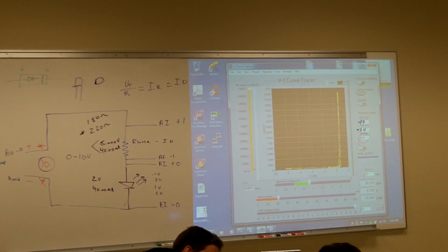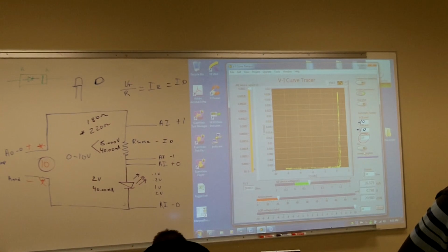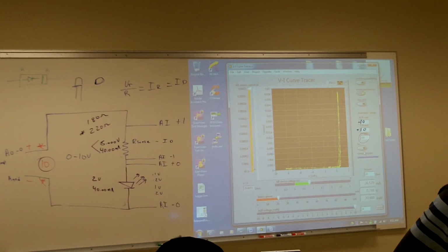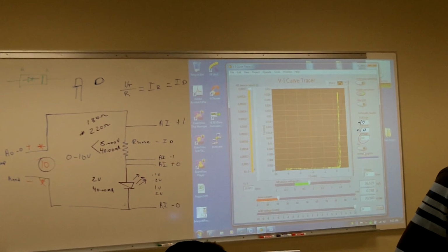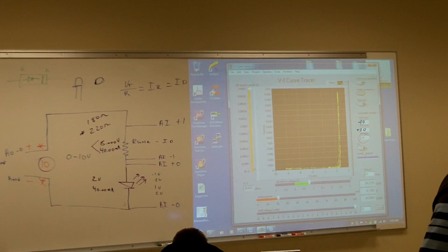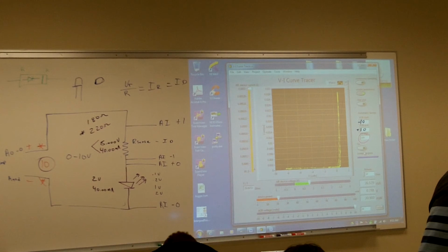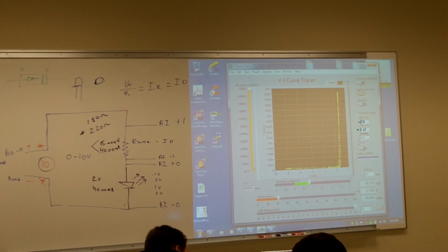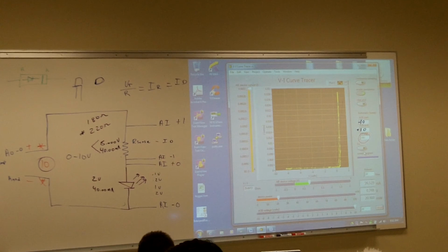So since you don't know what the specifications are, run the curve tracer. Did it work? It went into a reverse. Did it change colors or do anything different when it went into reverse? You might have started going into reverse breakdown, drawing more current than it really wants to. I didn't think we could even get that much current out of our setup. You reprogrammed it, made it better.